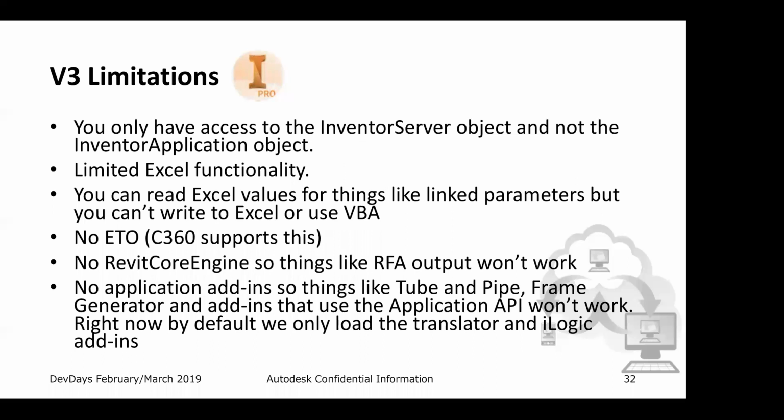About Inventor, as I said, we can use Inventor Server, not the Inventor application. A few Excel features are still limited. We can read Excel values, but writing or using Excel just like on desktop in VBA is not possible, because Excel is not installed inside Design Automation. It's just Inventor, right? We don't have ETO or C360 support.